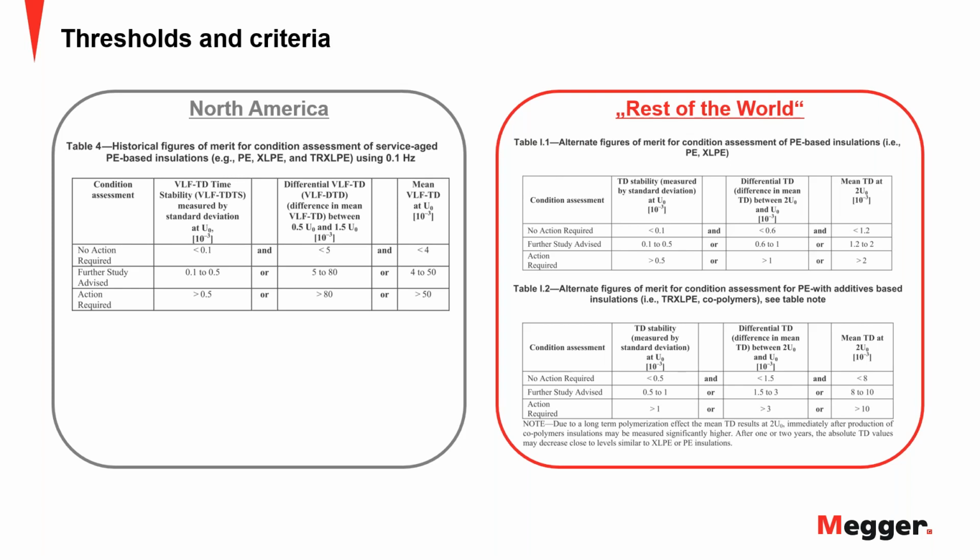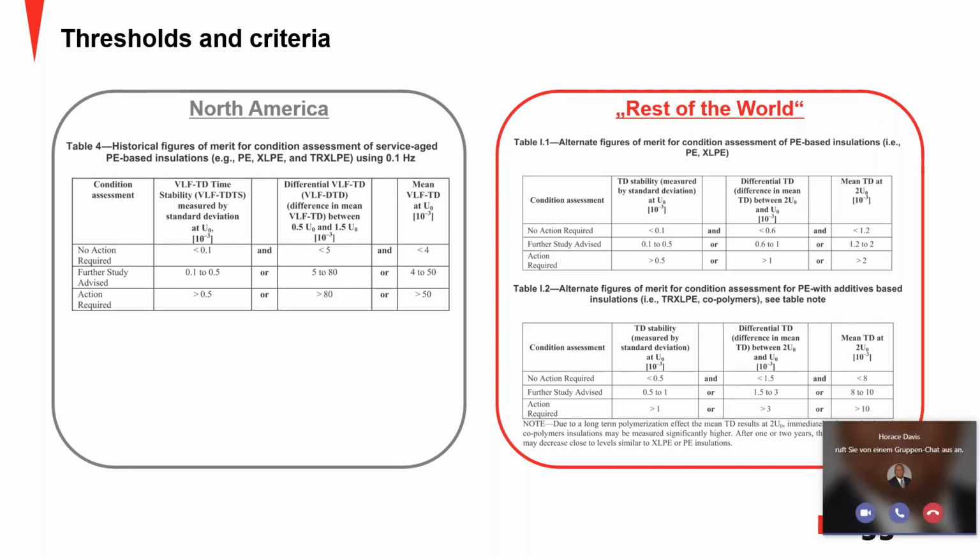So what a lot of our customers are doing is either they don't care about tan delta at all. I mean, it has its place, but a lot of people don't really care about it. They care more about the PD test. And another thing is they don't do the tan delta testing until the cable is really service aged, something like at least a year under load, or we have customers that wait 2 years. We have customers that wait 5 years. The extreme example that I've encountered was 7 years. So they have work procedures because they got burned in the past.